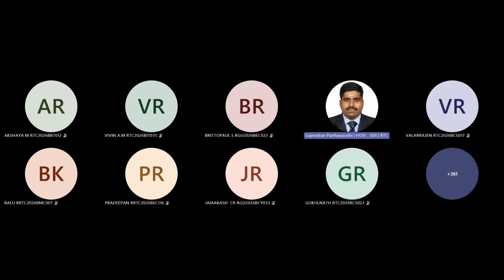If you give 0, the buzzer should turn off. If you give 255, it should turn on. Try and tell me. Quick. Am I audible? Reply in chat. If I give 0, the buzzer should be off; with 255 it will be on. Check and see. If you do that, then we will try with the variable sounds.